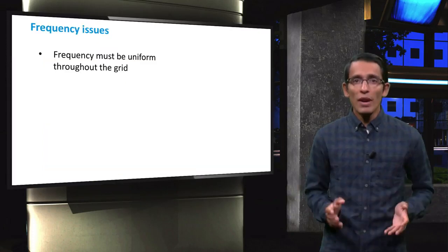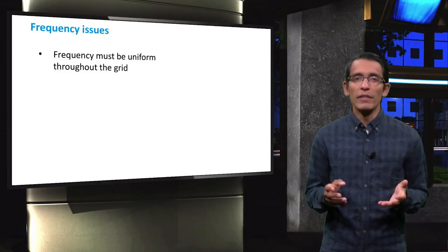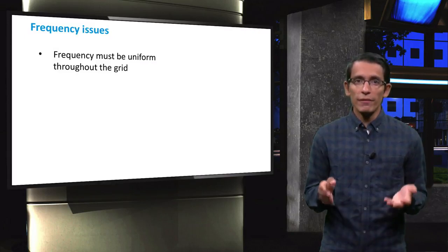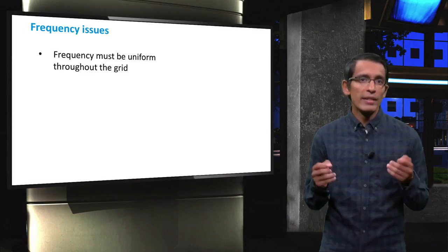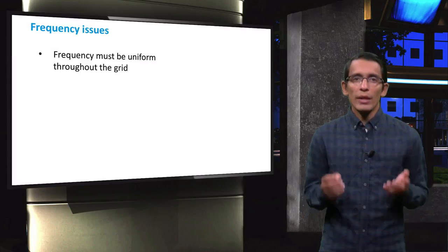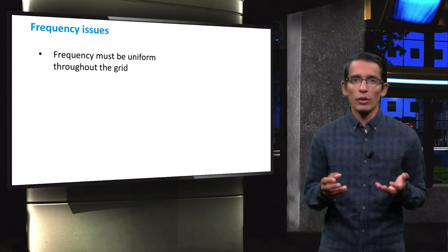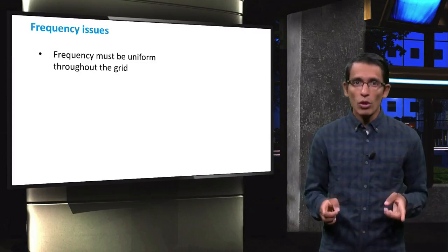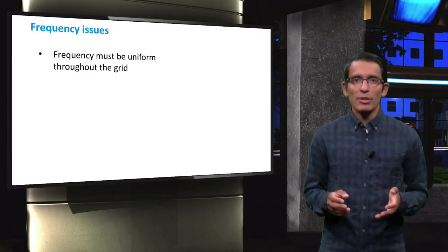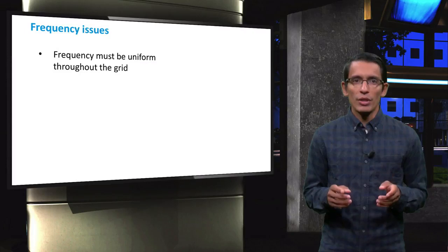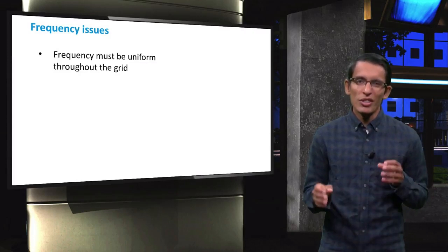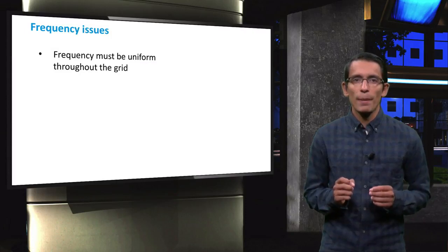Another aspect that can be affected by PV is the grid frequency. The grid works at a constant frequency of 50 Hz in a large part of the world and 60 Hz in the Americas and parts of Asia. In order to avoid problems with the functioning of the loads, frequency must be uniform throughout an interconnected grid. Control loop mechanisms built into the power generating sources are able to maintain a balance between connected load and generation with a small deviation in frequency.